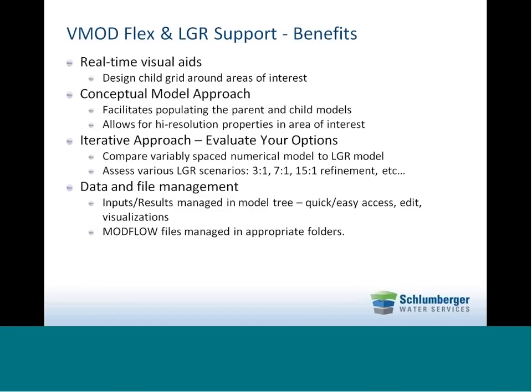Quite often if you're designing regional models, you may have more detailed borehole logs in a specific area of interest, so you have higher resolution conductivity values, initial heads, etc. With LGR, you can populate that child grid region with a higher density surface or ASCII grid, and in the areas where you don't have as much data, you can have coarser properties assigned. Again, this is done for you automatically during the conceptual model conversion.